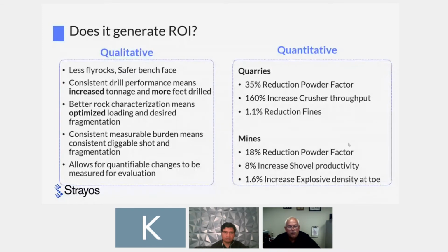Better rock characterization, absolutely. We have some of our customers that this is the only drill that they want because of that. They can tell when they have a change in their geology that they need to change how they mine and shoot based upon qualitative measures in the rock. They're not just looking for chemical analysis on the rock, and they can see that and be able to record where it happens based upon penetration rate and feed pressures.